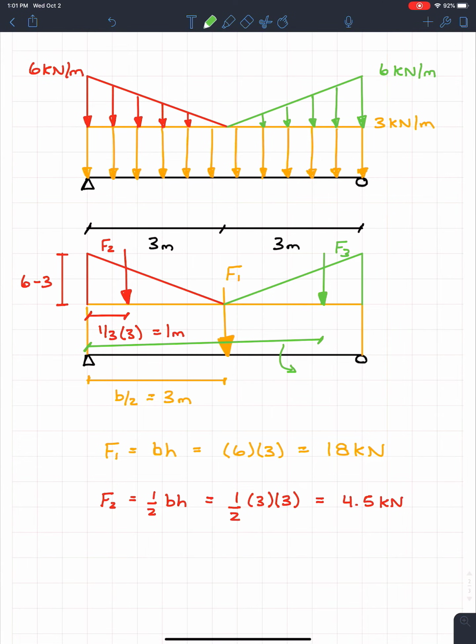And we know that that's going to be equal to the 3 meters. So that's just to get to halfway to the beam. And then plus 2/3 of the 3 meters, which is equal to 5 meters. So again, for the 3 meters, that's just to get from the left side to the center of the beam. And then we add the 2/3, which goes from the center of the beam to the centroid of the triangle.